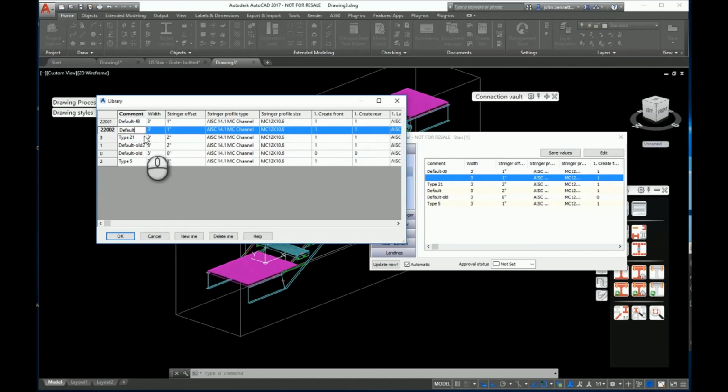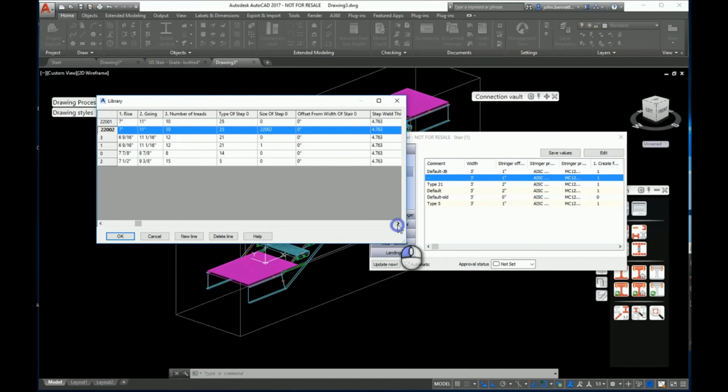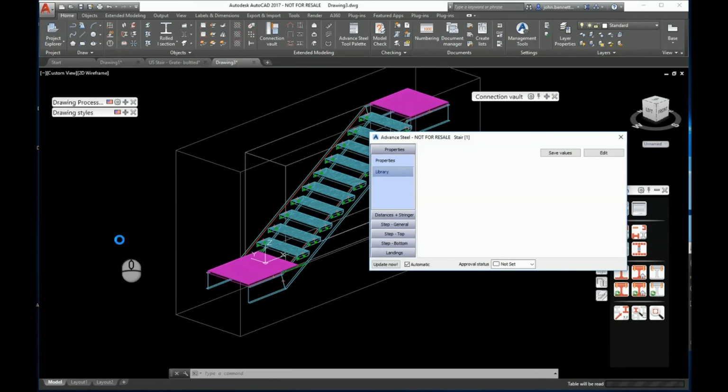You can see just by quickly looking in here, it's storing all the different parameters you set within the macro. So it is important to go through the macro and store all the different options, maybe cycling through a few of them, even though you might not need them. You can set them in here, and then they all get stored in the line in the database. There's quite a lot of them. I'm just scrolling through here quickly. There's literally every single button and tab you can see in there, stored in its own cell. Important thing when you've finished editing something is to go OK, so that will store those settings.